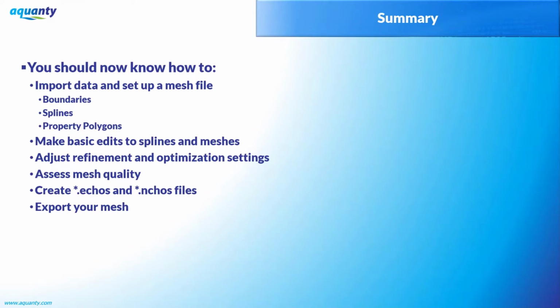The way that I would approach that, I wouldn't necessarily be doing it directly in AlgoMesh. With your exported mesh file, you could get the node list in GIS to select those elements, and then import that as a text file into AlgoMesh for those specific element numbers. It is actually possible to select all elements and nodes within a polygon. Oh, okay. I'll demonstrate that in the tutorial. Oh, perfect. Yeah.